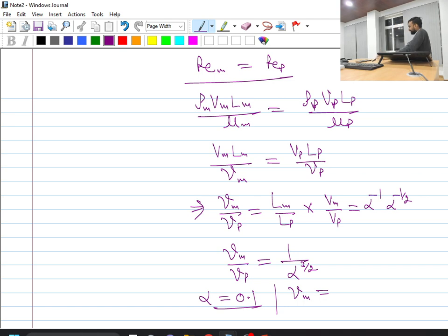So in a real scenario, you cannot find a model fluid which can satisfy your dynamic similarity, because some absurd value of the property will be coming, and that particular fluid will not exist in reality. If some close fluid does exist near that absurd value, that fluid will also have some challenges.